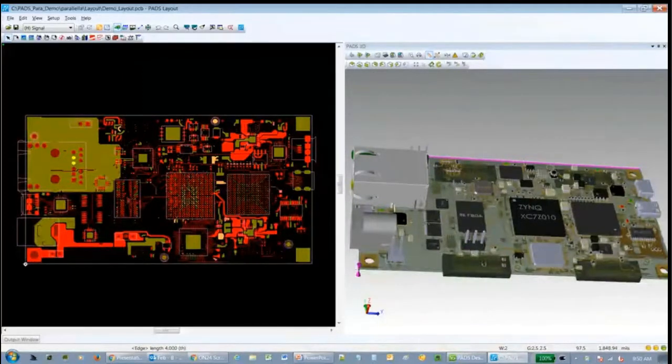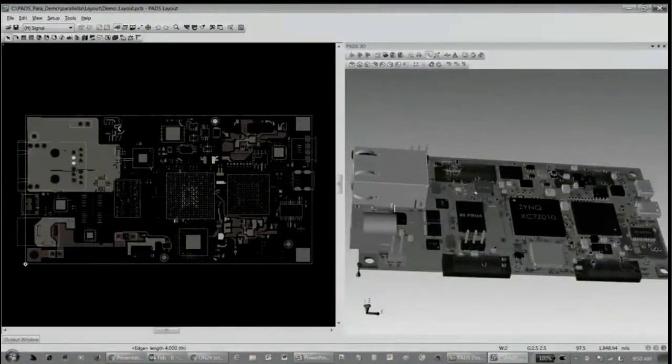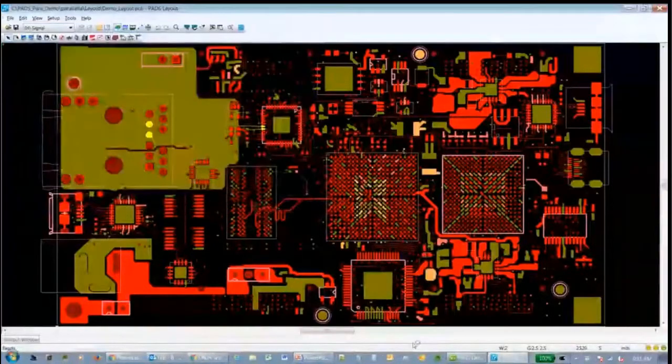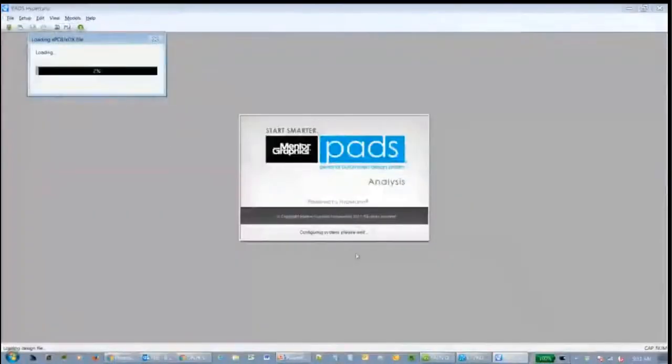Some other things that I can do here is I can go into some of our other simulation applications that you might have design issues with, like you're worried about signal integrity. I can launch this design into our signal integrity tool so that I can do simulation on either nets that I've launched up front, which I completely forgot to show. Let this go ahead and launch, and I'll show more on the schematic side.